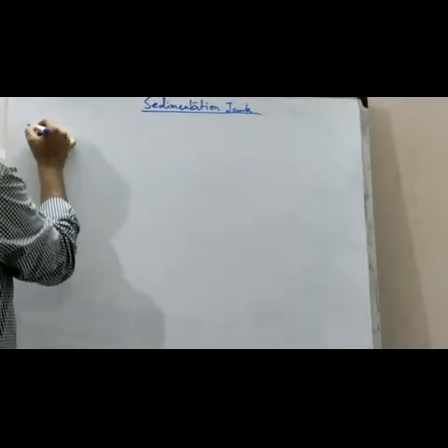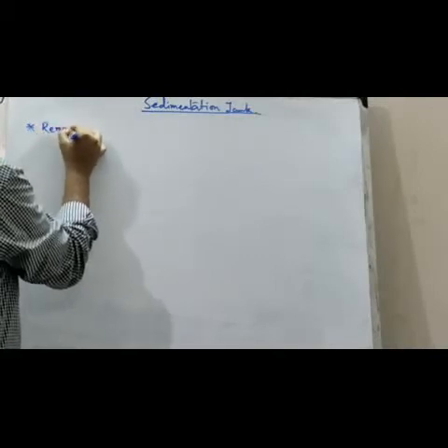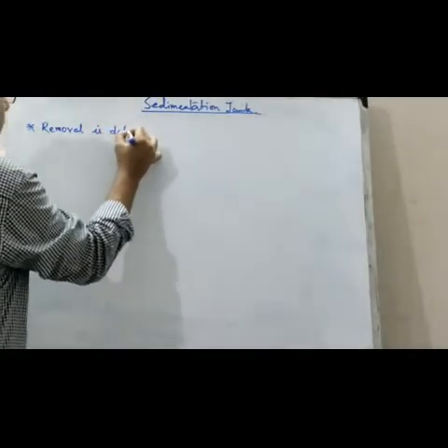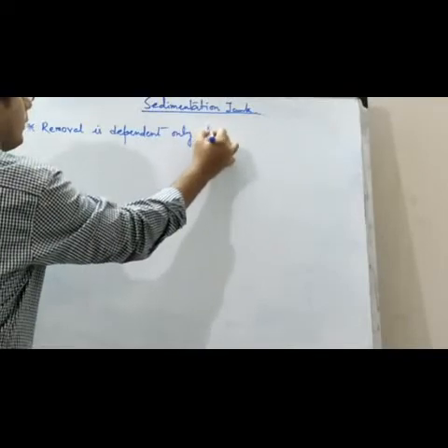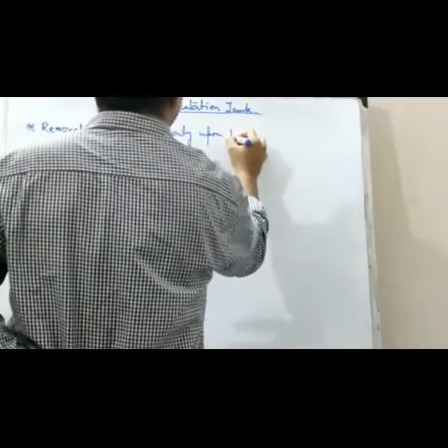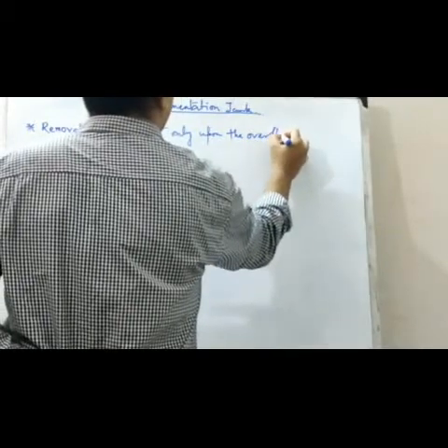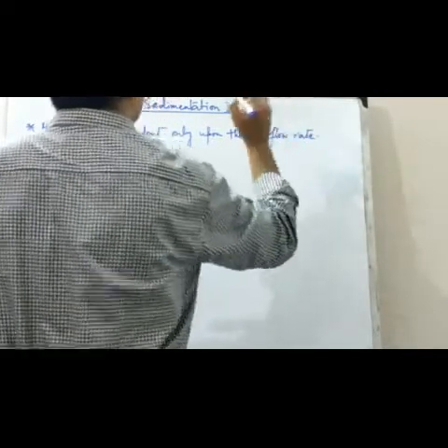So first of all, you have to know some assumptions in sedimentation tank. So in case of a horizontal sedimentation tank, we can similarly show that the removal is likewise dependent only upon the overflow rate. So the main thing is removal is dependent only upon the overflow rate.